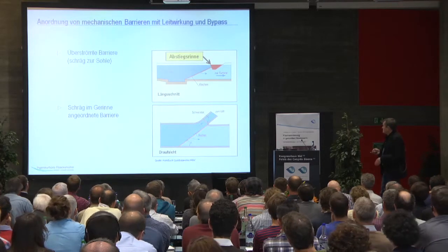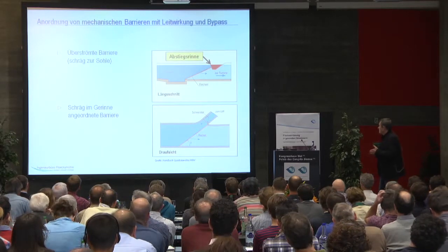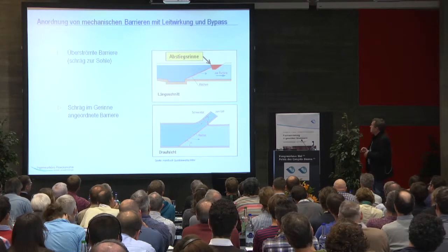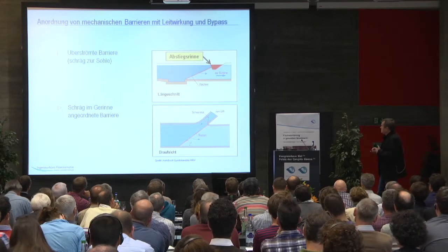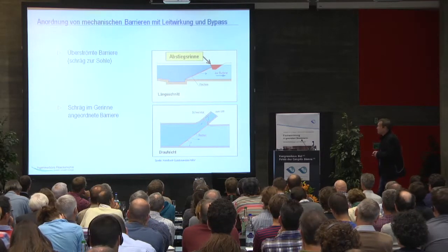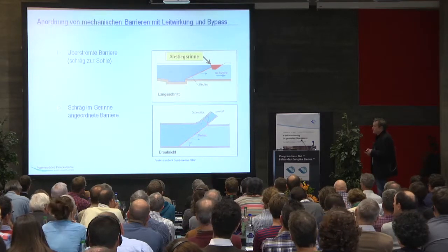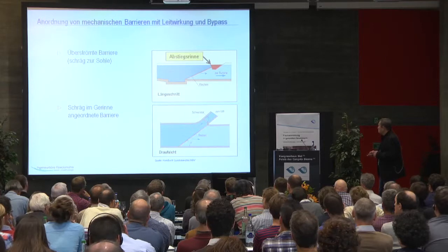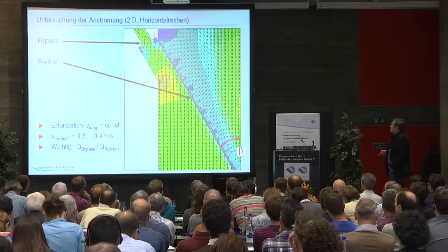A second version here: we have a vertical screen with horizontal bars placed in the flow direction with a certain slope, put into the channel. And at the end of the screen we have a volume, and there the bypass channel is placed, and then we have a closing gate, which can be a swiveling gate or another gate, and this controls the flow there.